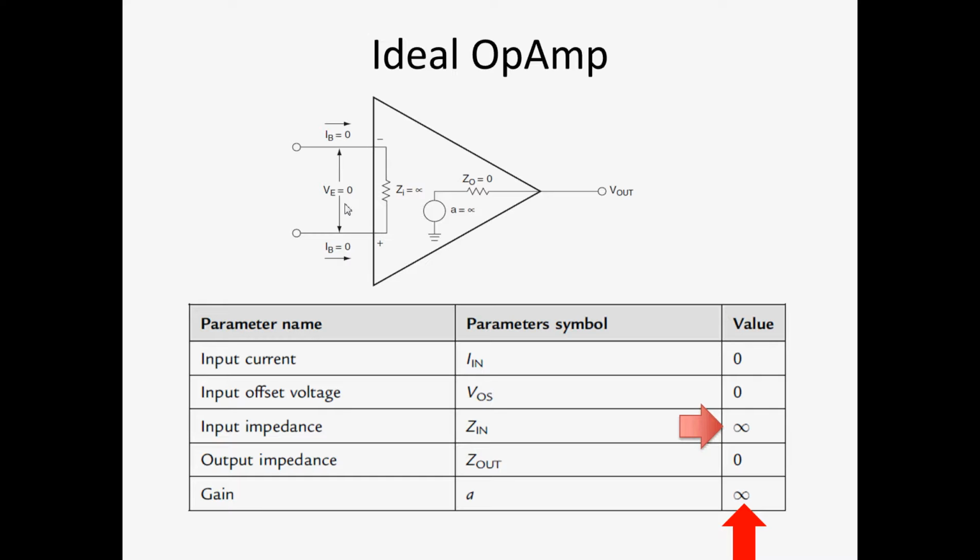You want this to be infinite because if there is another resistance connected between the pins of the amplifier, which could be the electrode resistance that we mentioned before, you don't want to change in any way that circuit. You want to observe it, right? You want to treat your signal like a movie that is happening, and you're just sitting and relaxing in the movie theater and you watch it.